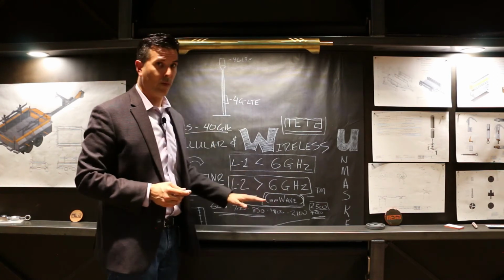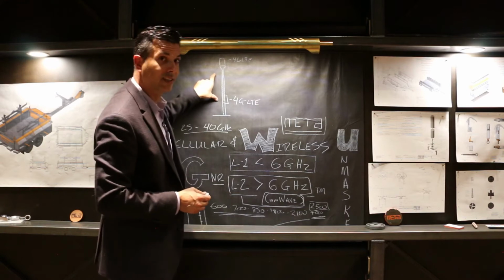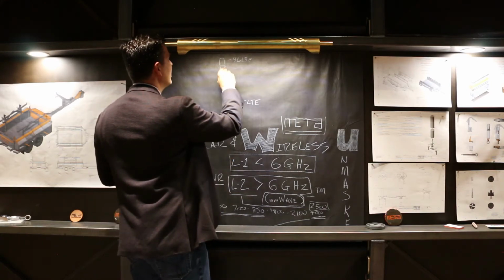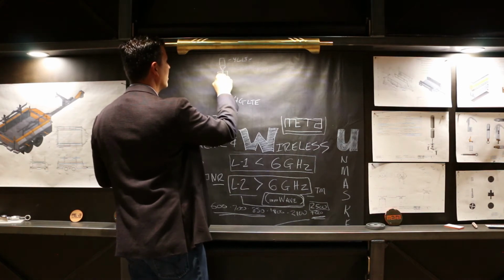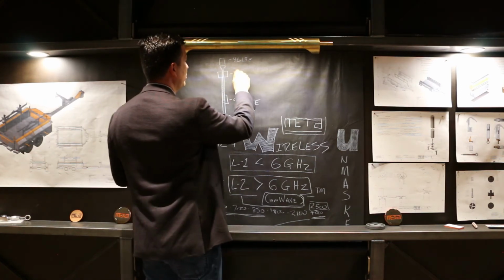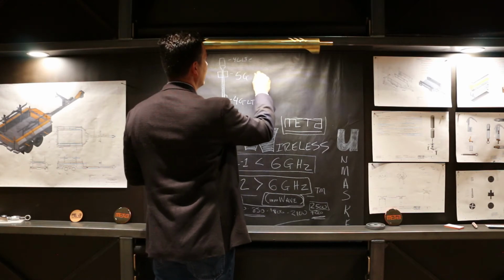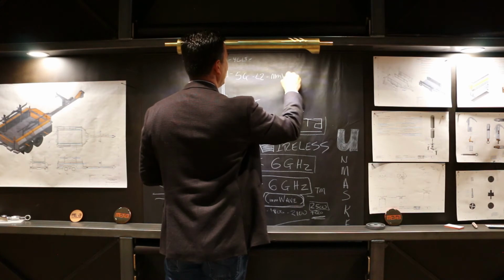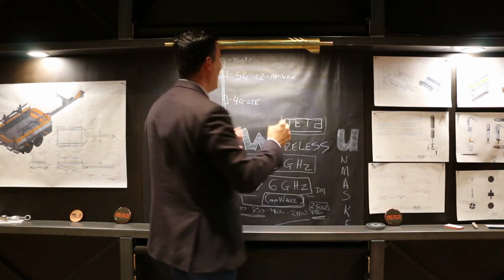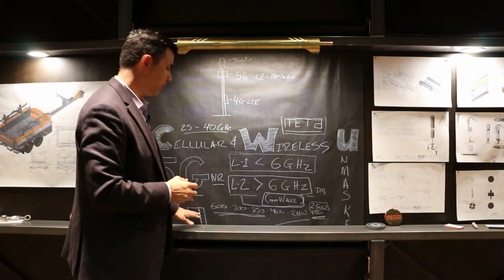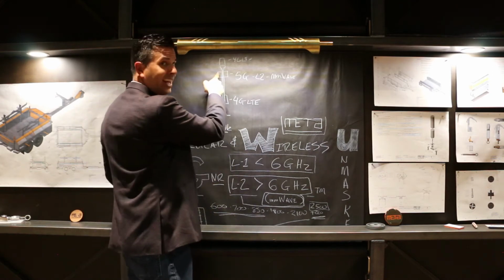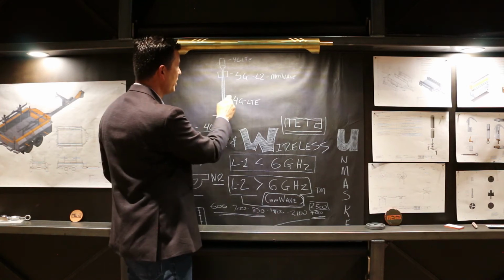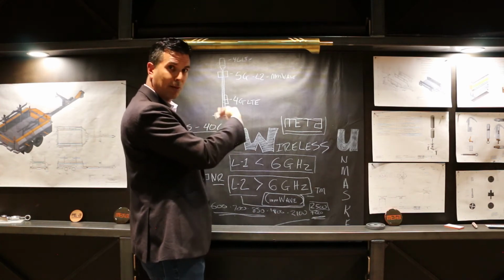Now, with the millimeter wave, you can't, because the attenuation, the signal loss in that cable is going to be too high. So what they do is they have the radios right here, below the 4G. This is your 5G level 2 millimeter wave active antenna. So like we showed before, the antenna and the radio are one unit. So at your 4G radios down here, typically it's a couple different radios.